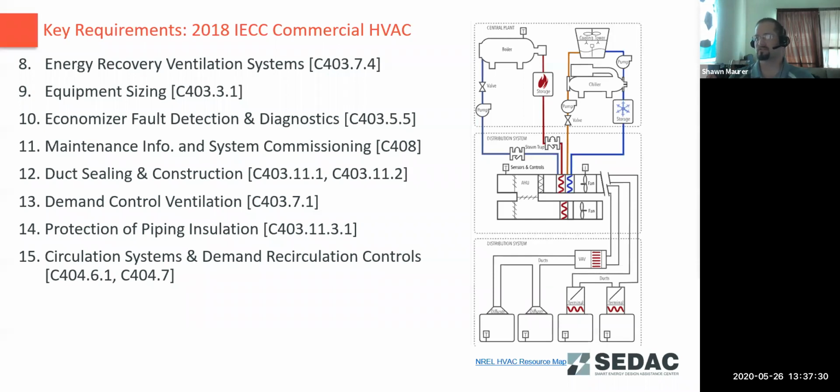So the curtain wall assembly as a whole is treated as fenestration, except where you've got kind of shadow boxes built into that assembly. Usually they are met through a U factor alternative for those areas that are opaque within a curtain wall assembly, but where it is open glazing that is allowing daylight, that falls under the fenestration assemblies U factor requirements.